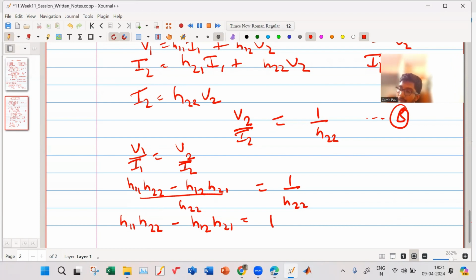I have a question. Here we are talking about hybrid parameters, right? In the Z parameter case we can open, and in the Y parameter case we can short the unnecessary ports, I mean the other ports. But for hybrid parameters we are also opening on both sides, right? So why should we open it? As per hybrid parameters, maybe we may need to short one port at a time, right? Why should we open it?